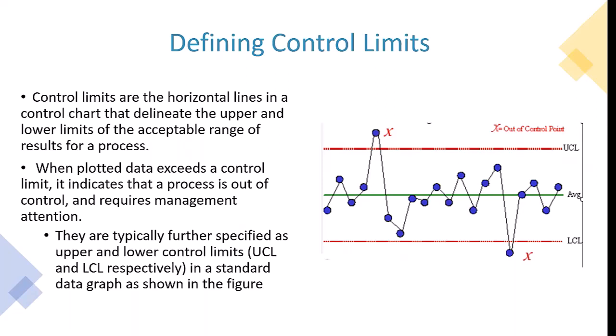And in a given set of data, there's always going to be bounds. You could say that the chart starts at 0, and that means the upper control limit is just going to be the only control limit that matters because the values can't be negative. But in most processes, you could measure an upper and a lower control, and within control would be anything within that range of values, and anything outside of that would be out of control.